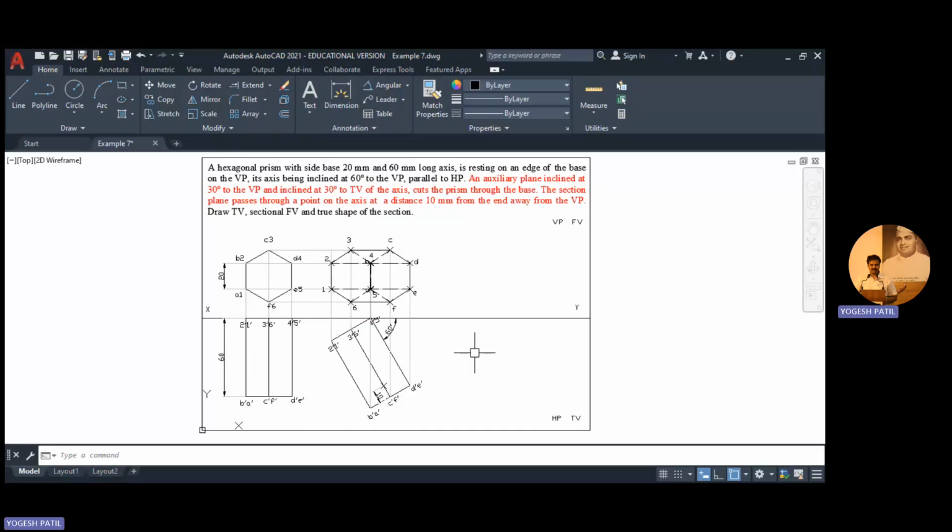So accordingly, we made the angle. So after that, we completed its front view, and we have maintained the visibility as this point 4 and 5 are away from the observer. So observer is observing this object from this end. So all the edges that are coming from 5 and 4 are dotted. You can see it over here. Okay. And remaining edges are dark.